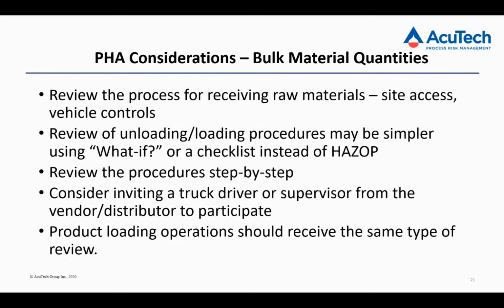Think about inviting a truck driver or a representative of the distributor, someone with practical experience, to participate in the unloading PHA. Now, you might be doing an entire process, and the unloading is just going to take one day or half of one day of a couple-of-weeks-long PHA. So bring the operator in for that half a day. The driver in for that half a day, and you'll be surprised what you might learn from that interaction. Again, just as good as having the operators in the HAZOP is having the guys that are actually doing the work there.